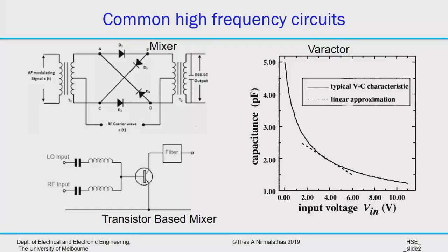All right. Or a very simple mixer could be just a basic BJT, because a BJT is, again, a junction of two diodes in a particular configuration. So the diode's exponential characteristics come into the BJT as well. If you bias it where the diode is in the turning on and off transition, then you can create a nonlinear transfer function that can mix two signals and then create a difference or a sum of two frequencies. So again, that device has a nonlinear transfer function because a BJT has exponential underlying characteristics.